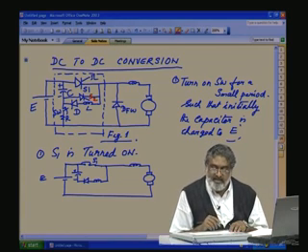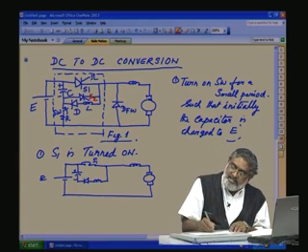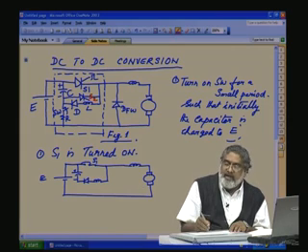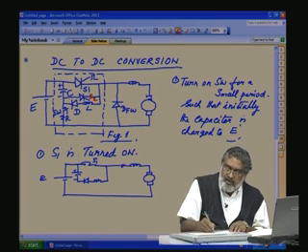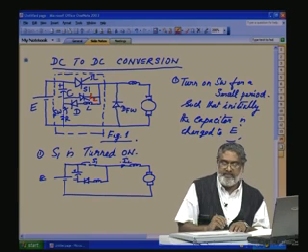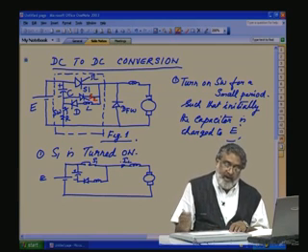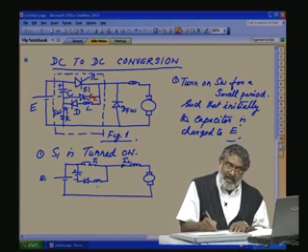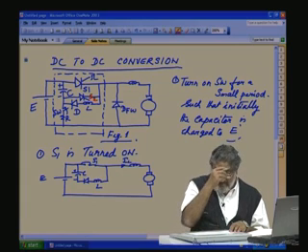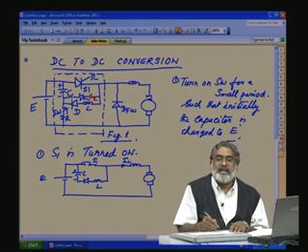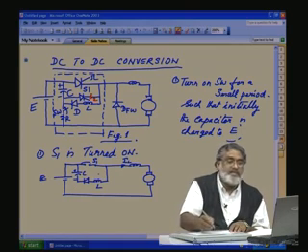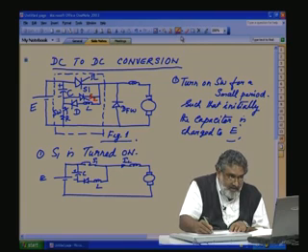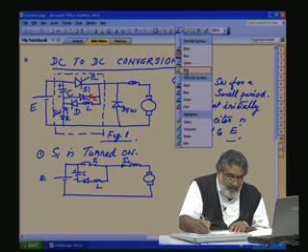So, the moment it is turned on, the load is a DC circuit. Because of the high inductance, the load current will flow here as DC, but because of this L and C, there is a resonant discharge of C, or resonant charge of C in the opposite direction. Through which path? The L and C. So, we will mark that one with a different color, so that it will be visible.